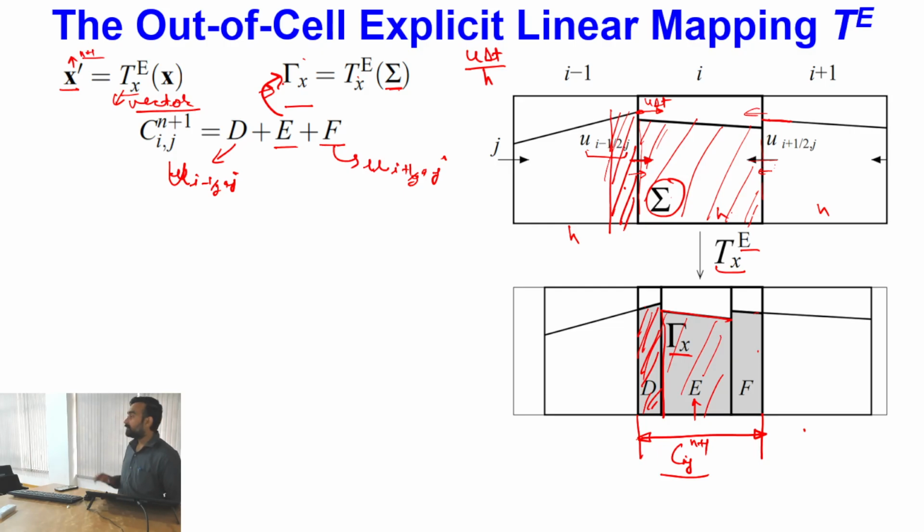So now you can see that you have not solved any equation, but geometrically, by just mapping the polygon, whether it will be expanding or contracting depending upon the velocity field, and how much will be the fluxes based on the non-dimensional velocities, you have simply estimated the new volume fraction of this particular cell. Okay, after you obtain this new volume fraction, your interface will not be this type of zigzag. If you keep your interface this type of zigzag, it will be giving you huge irregularities.